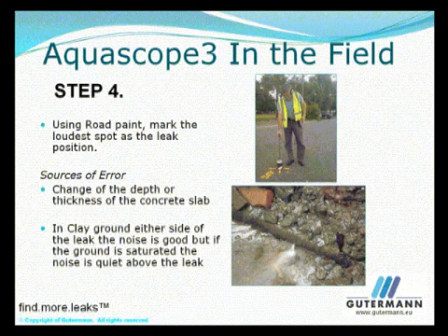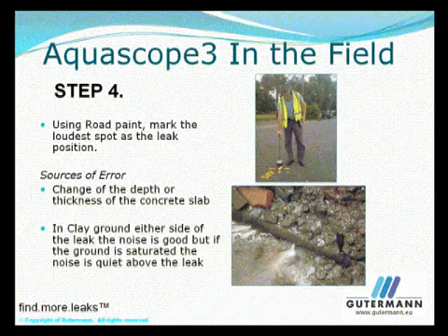Once you believe you've pinpointed the location with the loudest sound, confirm this position by moving the microphone back and forth to confirm no other spot in the immediate area gives you a sound equal to or more than the position that you believe the leak to be at.